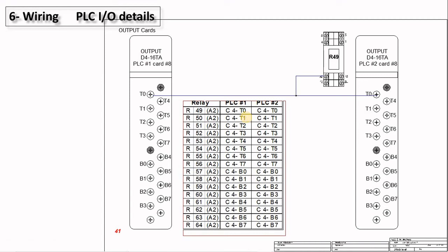So this is one method, but be careful when you do a drawing like this. Notice how I connect here, this wire and this wire. You don't know if you go from this to this and then one wire to the relay, or the other way around, or you connect them in the middle in the wire way, and then you go here.